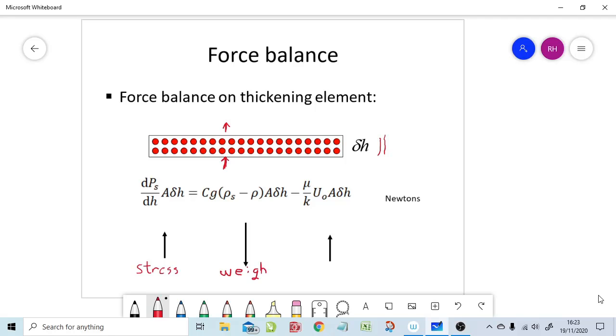Okay, what do I mean by the weight term is always present? Well, there's always a certain value of concentration, the acceleration due to gravity, the density difference, because we have a buoyancy force which we've brought into this expression here, and then again this is per the area of our layer that we're looking at, and the small but finite difference in height. Okay, that exists under all conditions, whether we have sedimentation or whether the particles have settled out.